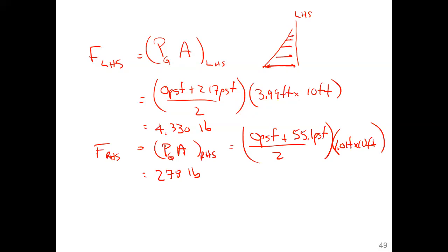Before, when we wanted to identify where forces on submerged surfaces acted, we used this equation, YCP, the distance along the inclined axis to the center of pressure. Remember that? When you use that equation and your surface starts at the surface, such that you have a triangular distribution, you will get YCP one-third up from the base of the triangle.